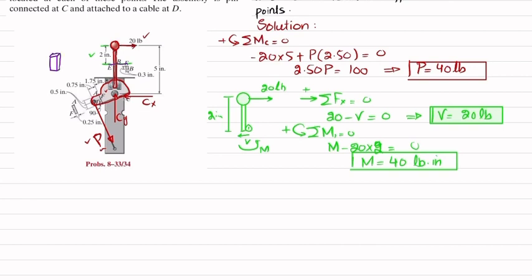There, this is your point E, and this is your point B. And since you can see the bending moment will be like this one, so if this is the neutral axis, so you can see the upper portion above this will bend like this. So point B will be in compression. We know that bending stress is equal to minus M into y divided by I.